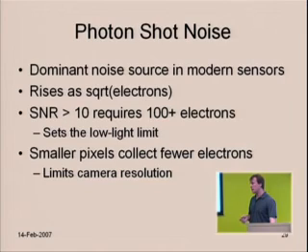The readout noise levels, for instance, in a Canon 5D, or for that matter any one of the Canon 8 megapixel point-and-shoots, are all about three electrons of readout noise. You can see that you need 100 electrons just to cover the signal-to-noise for this process. So the 3 electrons of readout noise is not significant, and they could make it 0 and it wouldn't improve things very much.